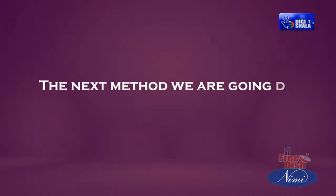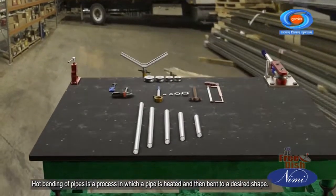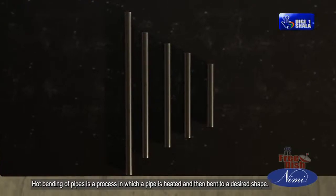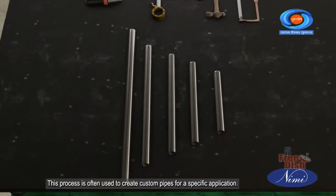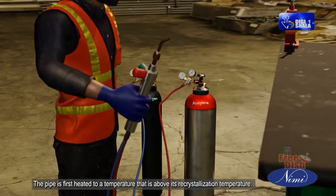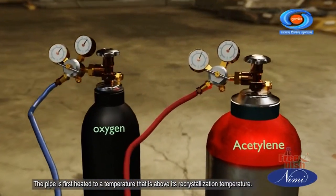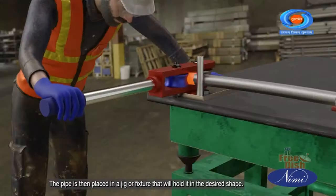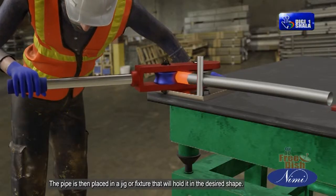The next method we are going to see is the hot bending method. Hot bending of pipes is a process in which a pipe is heated and then bent to a desired shape. This process is often used to create custom pipes for a specific application. The pipe is first heated to a temperature that is above its recrystallization temperature. This temperature is usually between 800 and 900 degrees Fahrenheit. The pipe is then placed in a jig or fixture that will hold it in the desired shape.